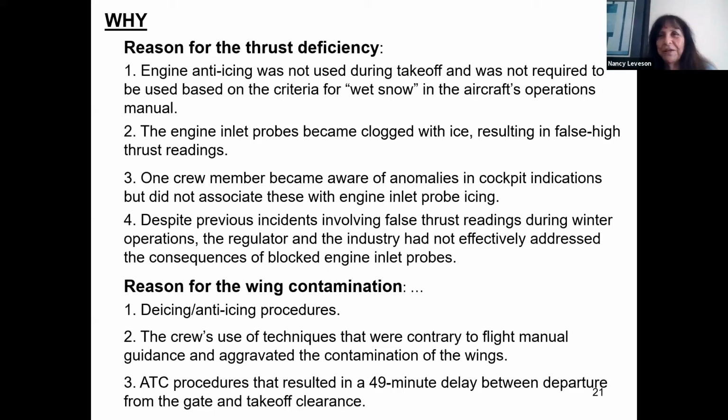Now we can do something about this. We can, besides fire the pilot if they're still around, now say, why didn't they associate it? And how can we change training? How can we change the cockpit design? How can we change whatever to make it easier for them to make that association? And number 4, despite previous incidents involving false thrust readings during winter operations, the regulator and the industry had not effectively addressed the consequences of clogged engine inlet probes. All right, more information that didn't come in when we were focused on what the pilot did wrong.